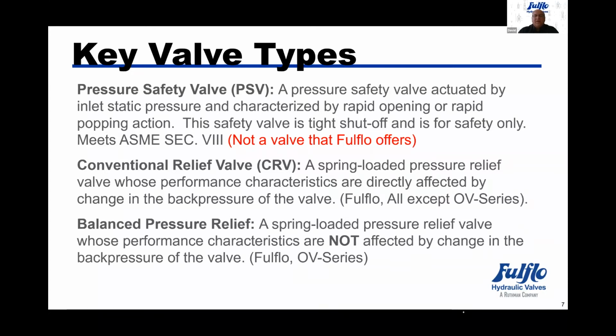But the full flow valve is more of the conventional relief valve, regulating valve, modulating valve, whatever people want to call them. They're really classified as a conventional relief valve. The spring-loaded pressure relief valve is where the valve would open, controlling pressure, but it does work off of the differential back pressures.